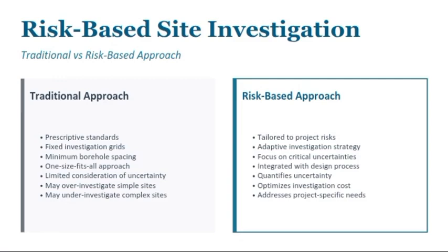It also meant that boreholes and tests were conducted according to fixed patterns. The objective usually was to collect large amounts of data. Little emphasis was placed on identifying the most critical uncertainty. And while this approach produced useful information, it often resulted in unnecessary testing, because it's the standard, so you just have to do it even when it's not necessary for that location. This increased project costs, caused delays, and sometimes failed to identify the most dangerous risks. And that's what has led us to this new approach, which is the risk-based approach. It changed the philosophy of the traditional way.